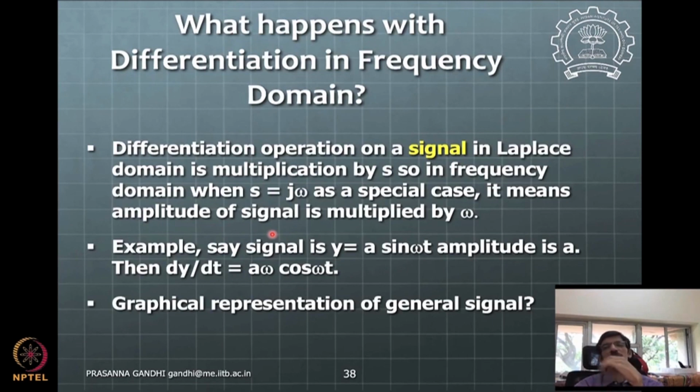Say, where we do this kind of operation, differentiation, for example for your motor, if you want to implement PD control, you take the value of your encoder and use some kind of difference formula, differentiating the encoder values numerically, and getting your speed. This numerical differentiation has some bearing on the noise. So it's very important to see what is happening with this differentiation operation in the frequency domain.